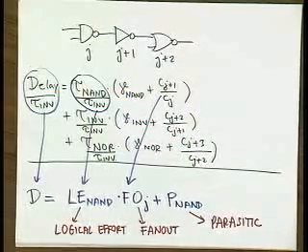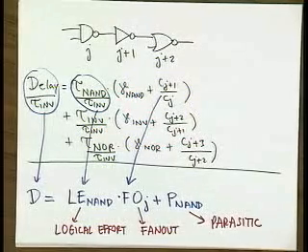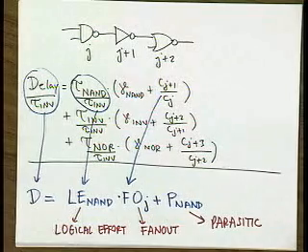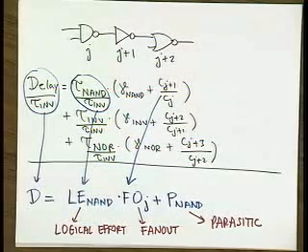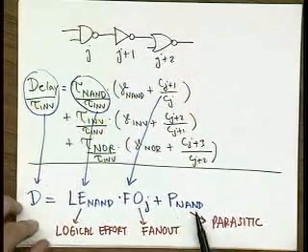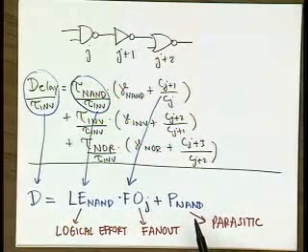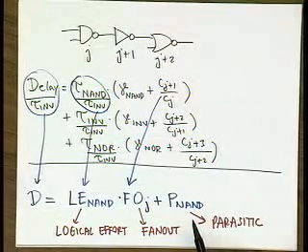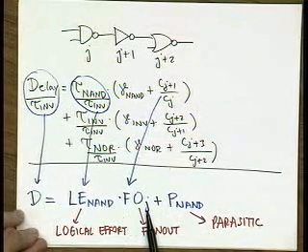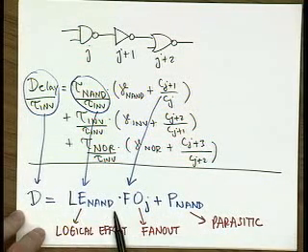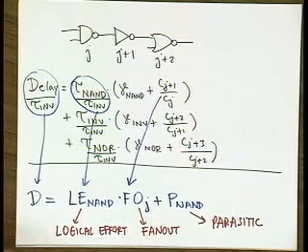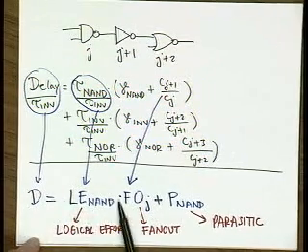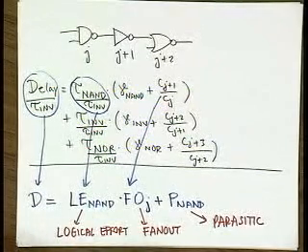Okay. Everybody all right with this? Okay, good. So what this tells you is basically parasitic delay is now your former TP naught, normalized to that time constant tau. So it basically just gives you the delay of your gate that is unloaded. And this is now the fan out delay. So it basically relates to the complexity of a gate and your fan out. So, and this is a very important parameter that kind of puts all this into a sensible form.